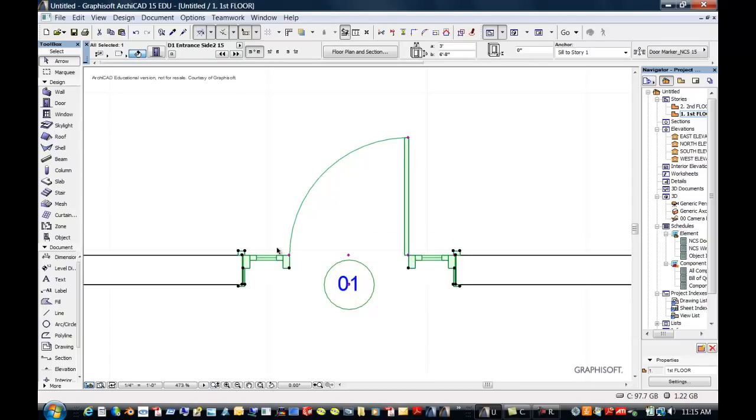Now say I want that swing to be over there. By selecting a grip, that brings up my palette of things that I can do. So these are things that I can do. Ignore anything you drag along because you're not really moving it. You're just going over here. So I can see that I can do moving, I can rotate, but anyway, I'm going to mirror and then come down and select that pink grip again, and we've basically mirrored